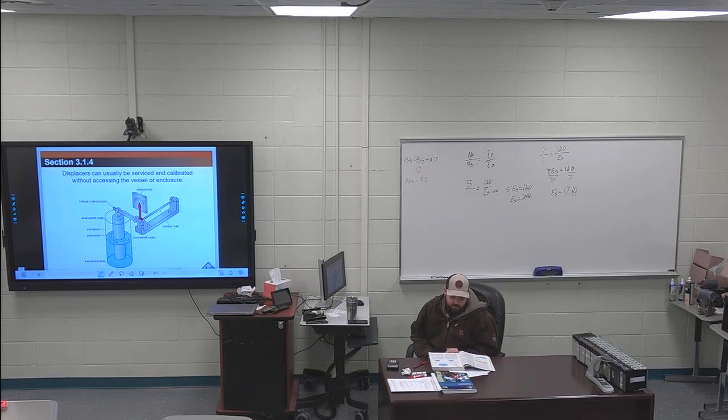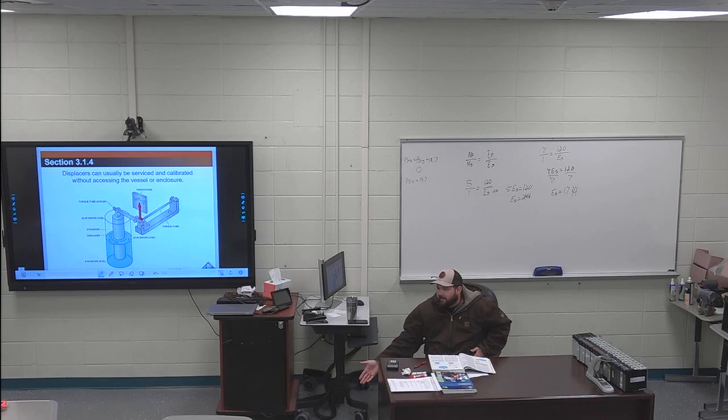Indirect level measurement. So an indirect measurement would be for everything else, right? Our direct is like taking a tape measure or a ruler, seeing what the actual measurement is. But nobody in here can go stick their hand in the Mississippi and tell what the flow rate is, right? You can't stick your hand on the surface of this desk and tell what the temperature of the desk is. So you have to take what's called an inferred measurement or an indirect measurement, which is getting one form of energy and changing it into another.